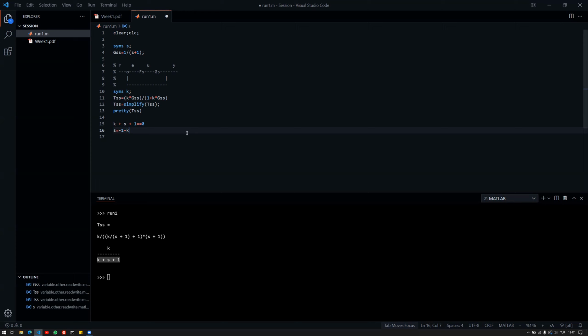I want to plot the root locus plot because that helps to understand how the system will behave, because what I'm really doing is having a parameter. I'm changing that parameter over an interval. And what I get is the position of the poles. So they will move around on the S domain, and I will get a certain position. And it will tell me when they pass the j omega axis, because that's the danger point. So if I'm passing it, then I will have some unstable poles. So therefore, we need a root locus plot.